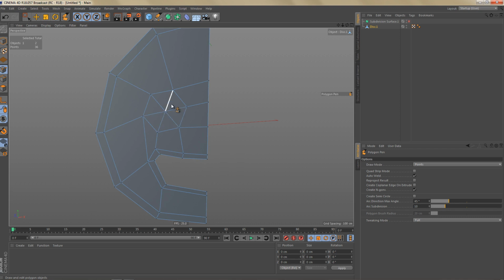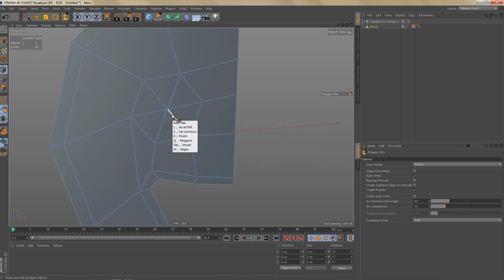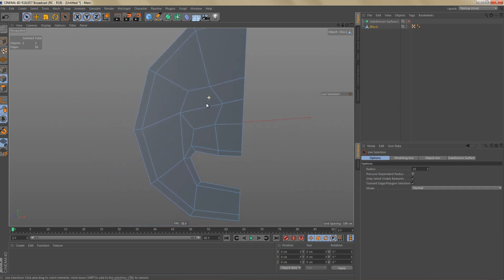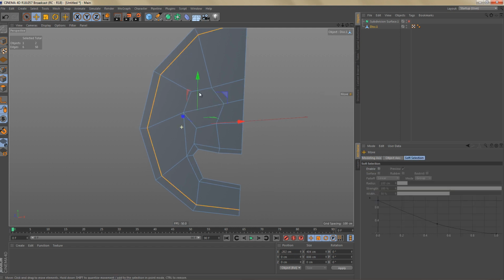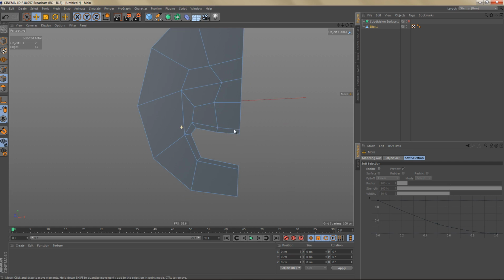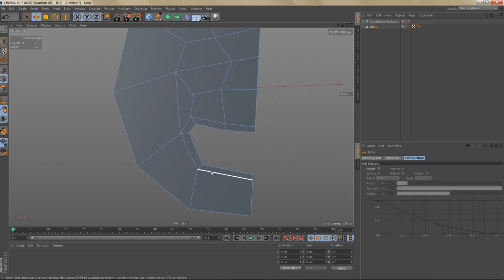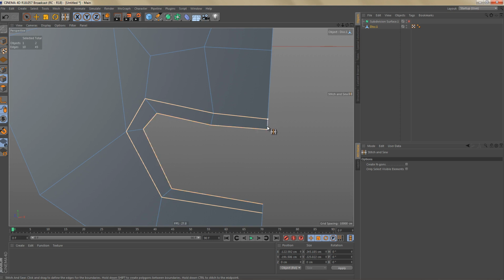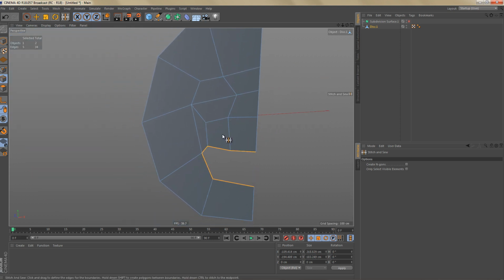We still have some triangles here on the eye, so I'm going to remove those by going to Edge Mode, selecting these 4 edges here, and we can simply dissolve these edges. So now we have 4-sided polygons. And for now I'm also going to delete these edges here. So let's dissolve these edges, and we can also get rid of these edges here for now. So I'm going to select those, and let's see, maybe we could also select these edges here and then use stitch and sew, and then just left click and drag from this point down to this point to get rid of this edge loop.